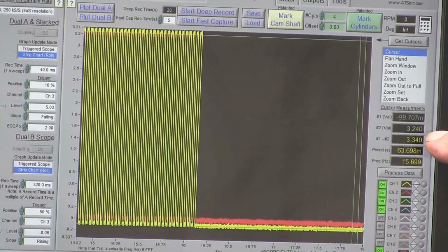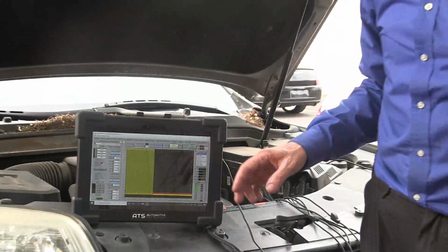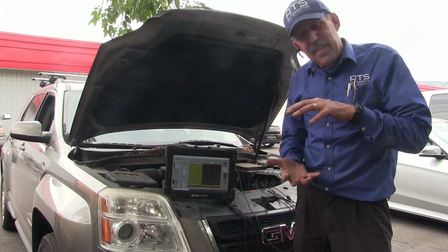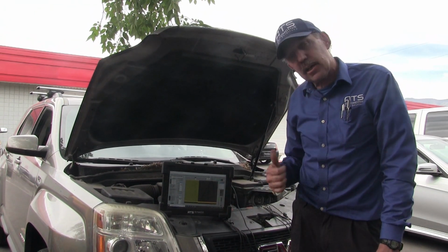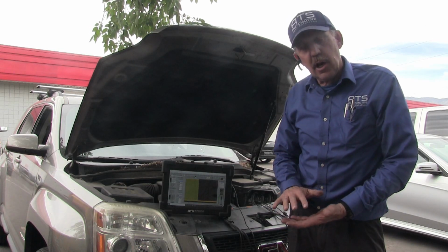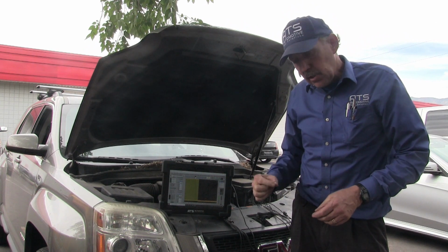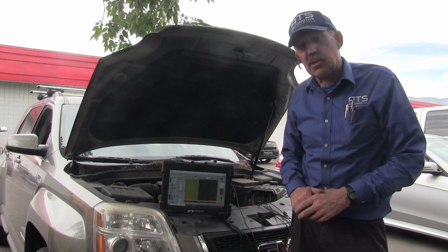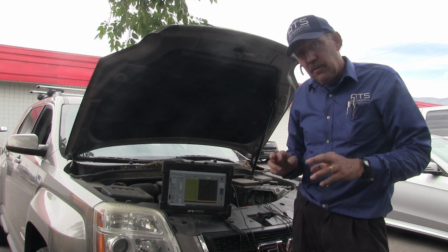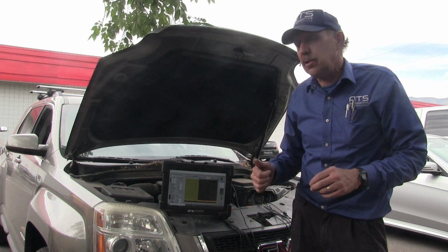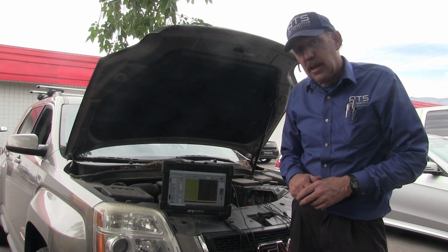So as we can see, we only got 3.2 volts on that. We don't have 5 volts, guys. Without having 5 volts, that circuit is loading. And if it's loading this circuit, it's going to load the O2 sensor circuit, so the O2 can't put out. So the O2 is being loaded, and there's also some problem with the bias voltage, because I'm still pretty sure most of these GMs I've checked are at 1 volt. So we have 2 problems. One, the O2 is being loaded by the circuit, and we have some kind of a problem with the bias voltage.